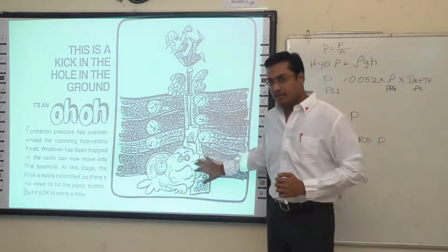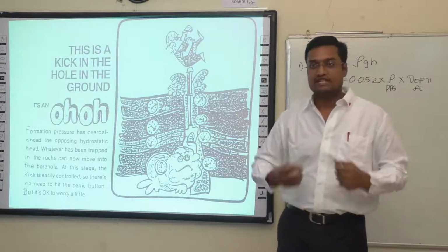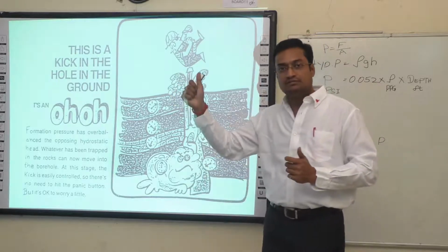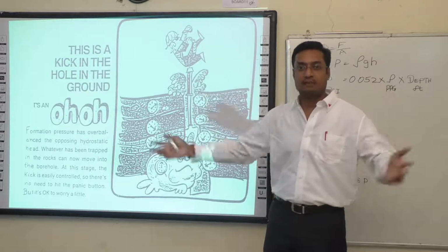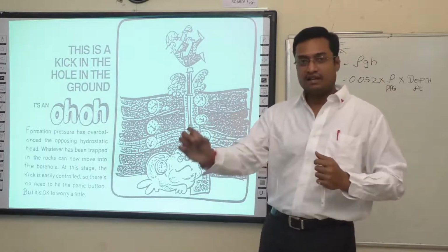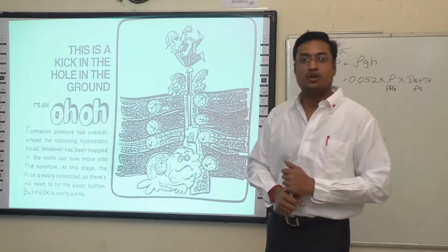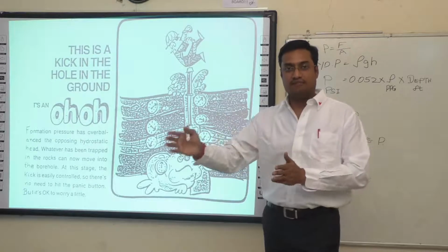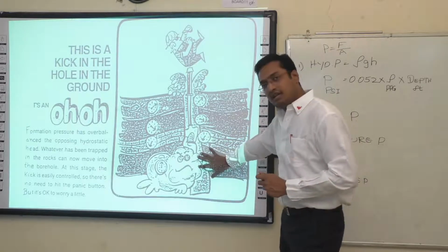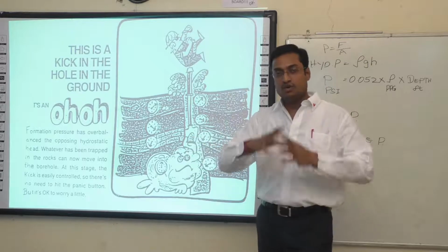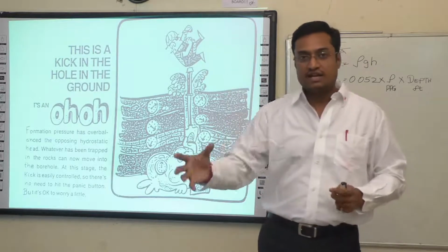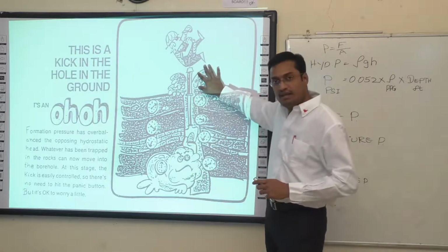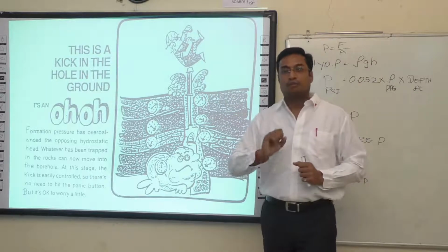So when you get an indication of a kick, it's like a slight fever. There is no need to panic, no need to press the panic button or shout or make everybody aware that there is a kick. A kick is a slight infection which can be controlled much more easily if it is identified in time. So when you get an indication, when you confirm it is a kick, you start taking well control measures. Circulate the kick out of the well, take control of the well, proceed with it.